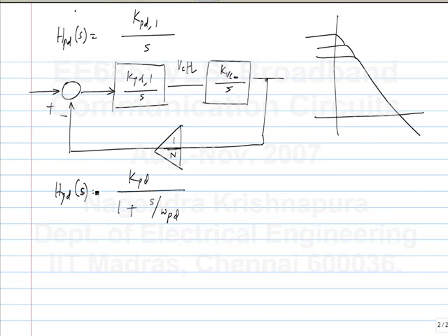What kind of, how would you assess a system's stability? And you see the phase margin. Anything else? I think you need to know the polynomial to do that, right? Approximated by a second order system. How will you do that? First of all, we only have a second order system, so we don't have to do much here. But yeah, maybe some terms are negligible in some cases. What else? Root locus. There are many techniques for evaluating stability. So if you are sufficiently familiar with it, I can go quickly through this.